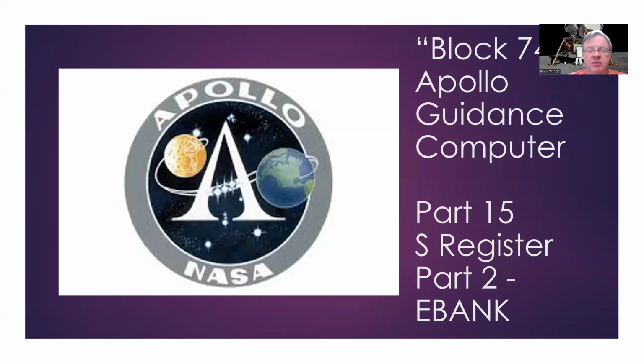Hi, and welcome back, everyone, to part 15 of our Block 74 Apollo Guidance Computer series. Today, we're going to continue talking about memory within the Apollo Guidance Computer. We talked about the S register a little bit in the last episode and about the memory mapping scheme within the Apollo Guidance Computer. So we're going to dive a little bit deeper into that and start talking about the EBANK register or the